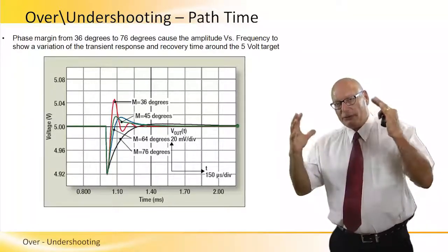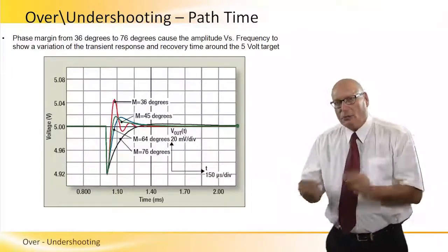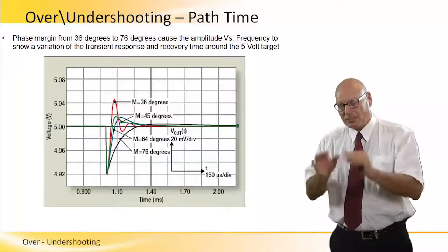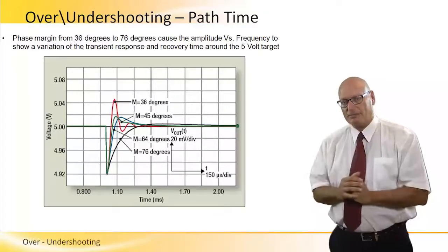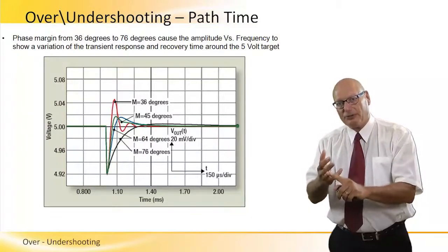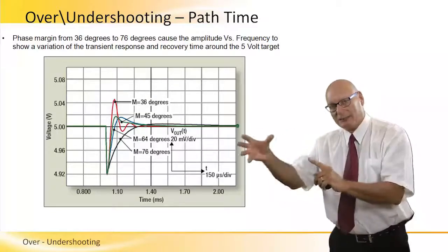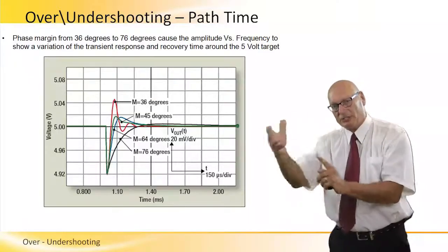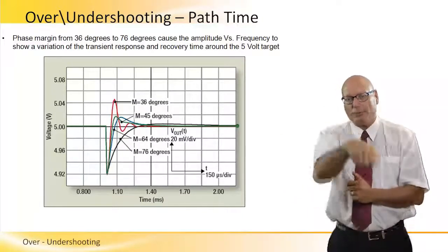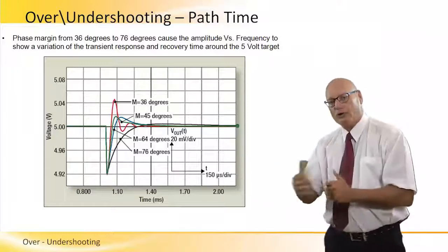So it's not very difficult to design a path with a known amount of over and undershooting. Just to repeat and summarize: we know the path, we know the allocated time to do the path, we know the robot, we can calculate the torque and all the mechanics and physics aspects of it, acceleration, deceleration. From all these, we get the Q, we plug the Q into the program. That's how we can control the path.